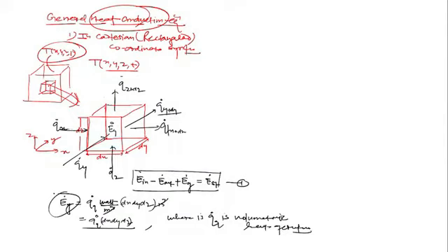Okay, clear? So you should be very careful whether this is Qg or Qm. Qm is the heat generation per unit mass, and Qg is the volumetric generation per unit volume. That you must be clear from the units. Is this volumetric or is it mass? Is this clear?